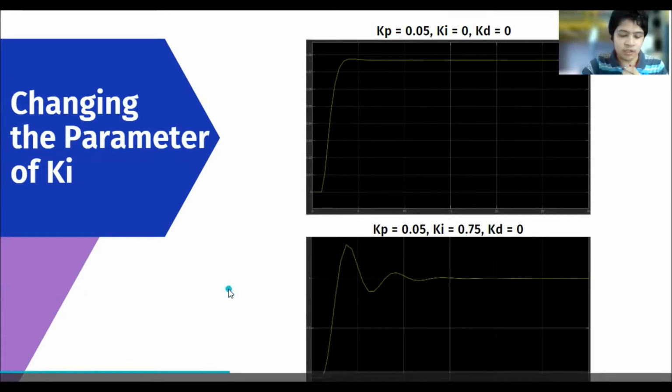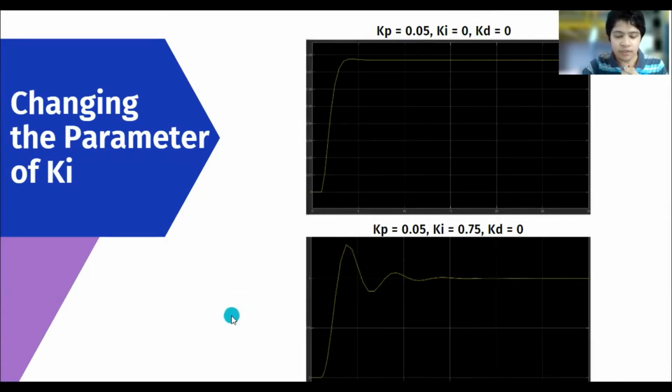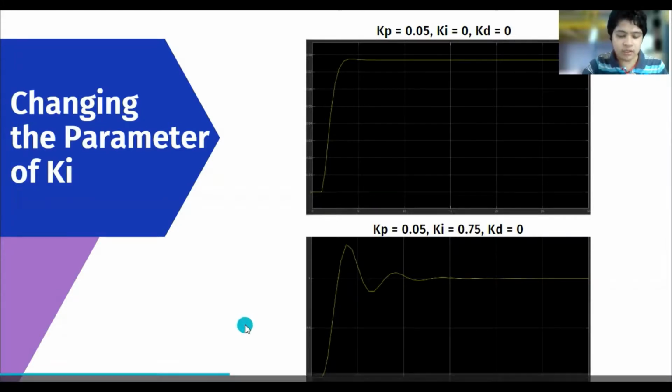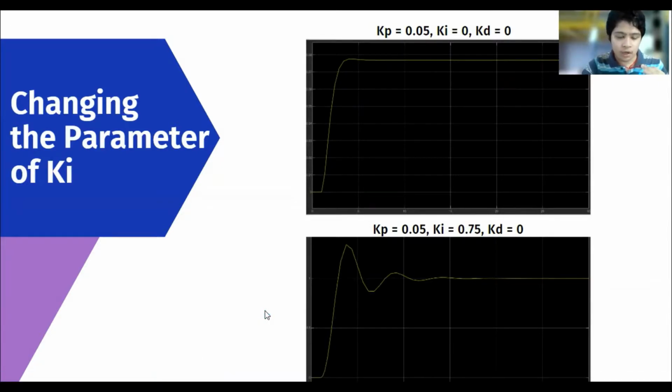This is because the integral coefficient in PID control determines how much control output is produced due to the accumulated position error, and by adjusting the integral coefficient, the steady state error may be eliminated, but may make the transient response worse if not adjusted properly.